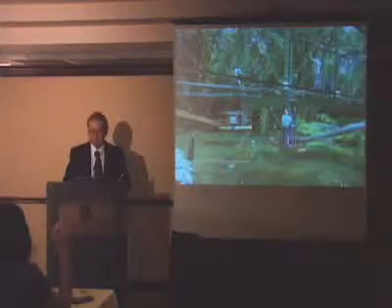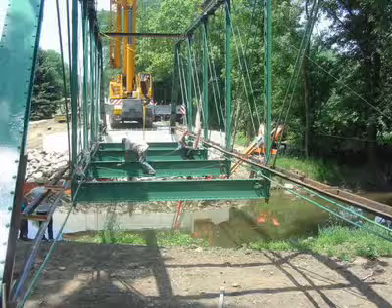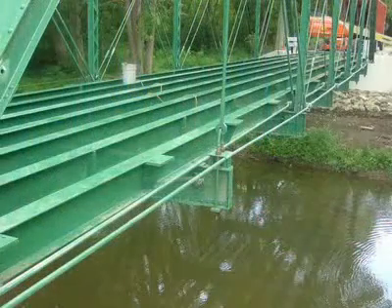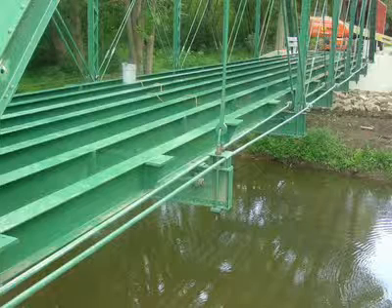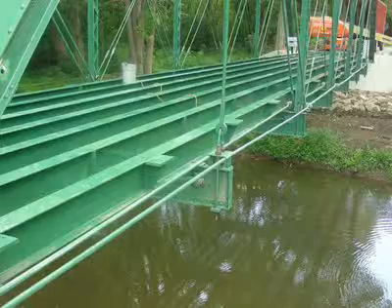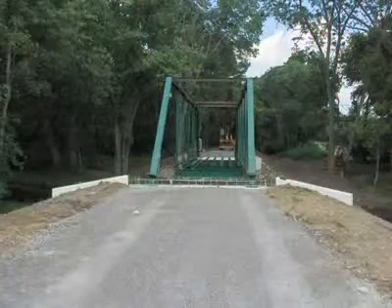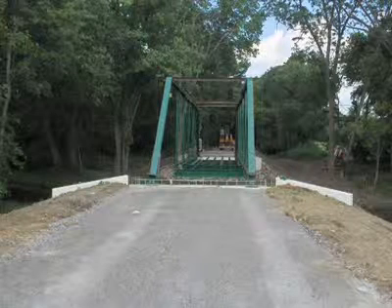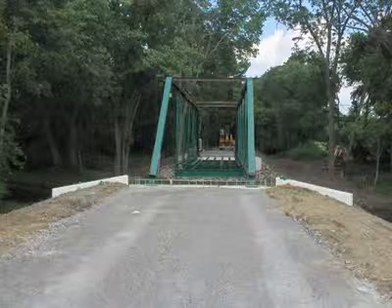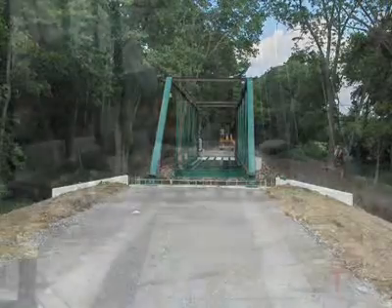The rest of the bridge was original. It did have a posting when the bridge was finished. I forget what the posting was. Here's one of the new units, that was new bars, the vertical bar that's here. All these U-bolts were replaced. Of course, the new stringers. The temporary bracing we used on top came out later as we put the original portals back in.